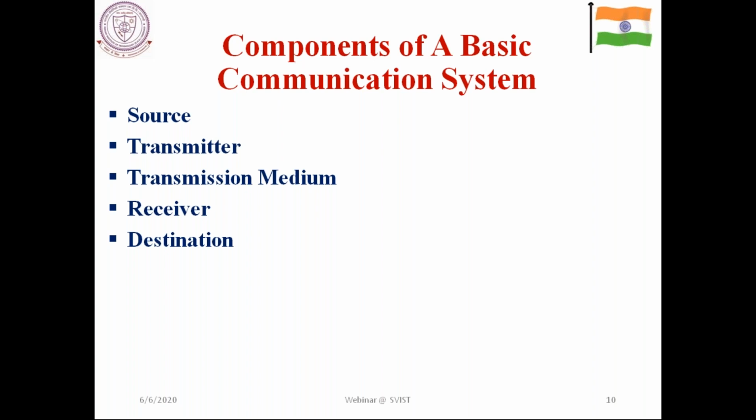Now, what are the basic salient features in a communication system? You already know why we need this kind of communication, or why we need modulation. The main thing is you have to realize the physical size of the antenna, right? The antenna is of the order of lambda. So once you go for the high frequency region, you are basically incorporating lower lambda, which is much easier to incorporate in practice.